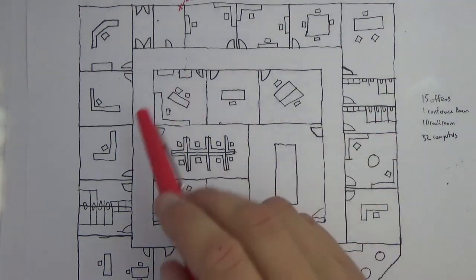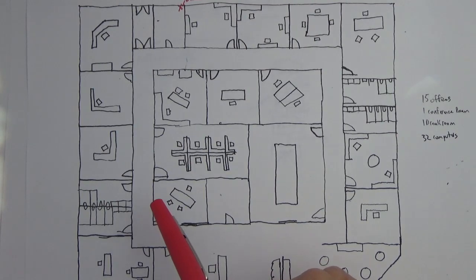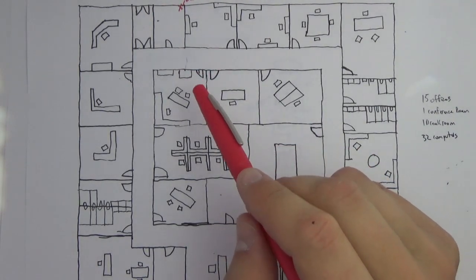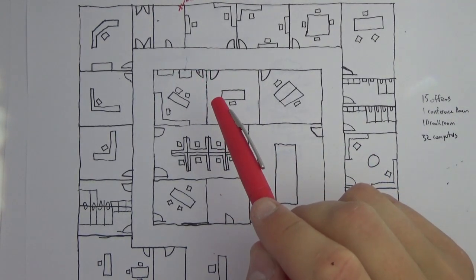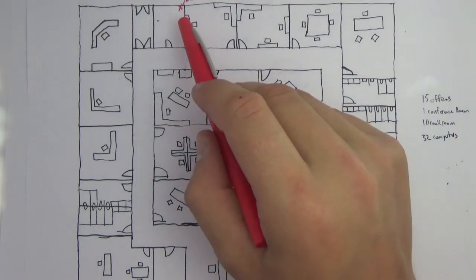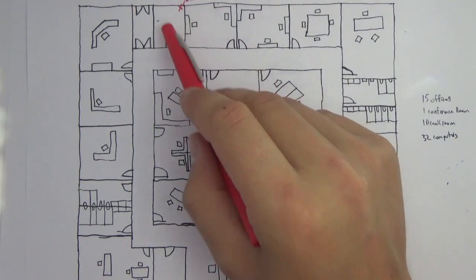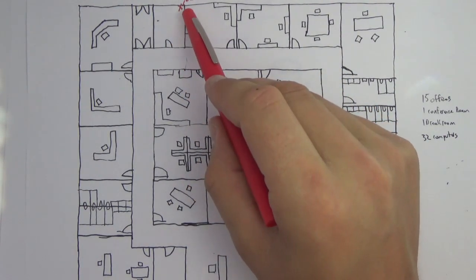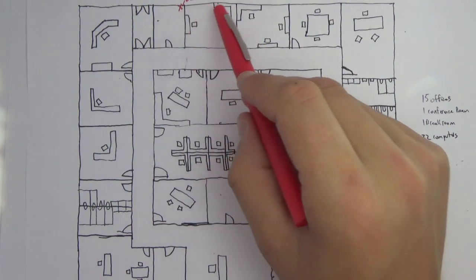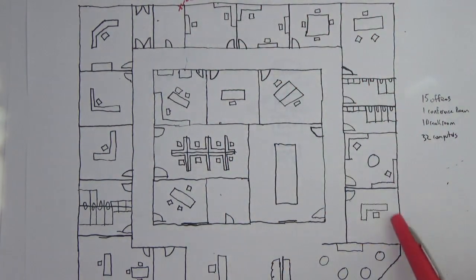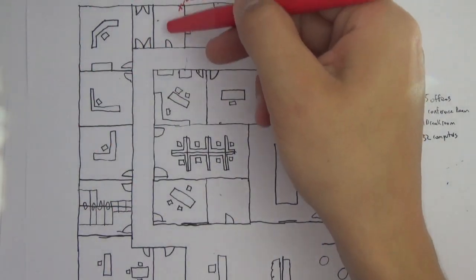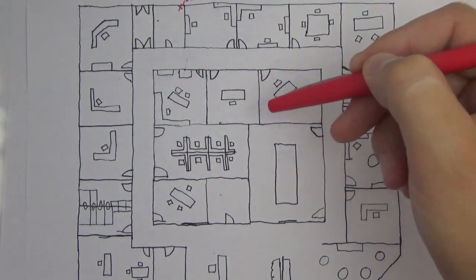Now, in an environment like this, we're going to have a lot of lines for both safety reasons, interference reasons, and because it's the right way to do it. We're going to want to put all of that wiring inside of a conduit of some sort, some kind of a gray PVC or something like that. So let's say with the basement option, if this room is our demarcation point, we're going to punch through. We might run either a cable track or a pipe along this outside wall, all the way around the building, maybe one leg going around that way, one leg going around this way, run something into the middle over here, and then pop up through the floor.